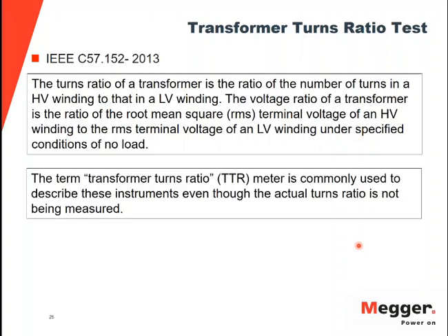You may have heard this thing that I have a turns ratio tester. The interesting thing is that any of those testers out there, they do not measure the turns ratio. They measure the voltage ratio, and it is assumed that under no load condition, the voltage ratio is the same as the turns ratio.